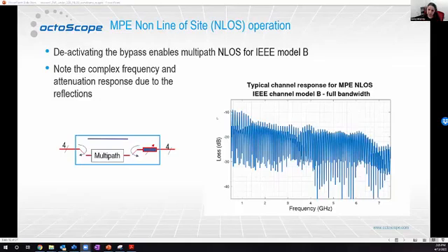But that's the over-the-air part of the test bed. Yeah, so that's a good point. The channel model itself, the MPE, is identical. But as soon as you hook up an antenna and you start talking about different angles of arrival, if you convolve that with the response of the MPE, you will hopefully get different frequency responses for your different antenna placements.